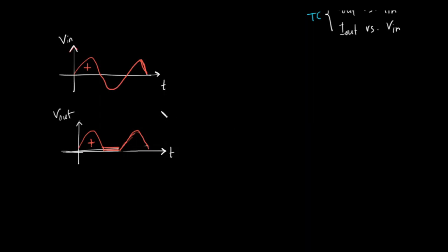But the drawback is you also have a voltage in the negative cycle at the input of the circuit, but you are not getting any voltage from that negative part during the negative cycle of the output. The output during the negative cycle is zero. There is some voltage in the input during the negative cycle, but you don't have that negative voltage in the output. So can we make some form of circuit that can actually use this negative voltage in our AC to DC conversion?